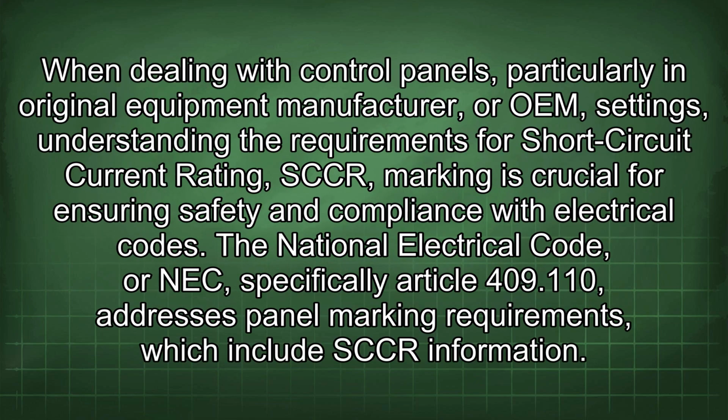When dealing with control panels, particularly in original equipment manufacturer or OEM settings, understanding the requirements for short circuit current rating (SCCR) marking is crucial for ensuring safety and compliance with electrical codes. The National Electrical Code, or NEC, specifically Article 409.110, addresses panel marking requirements, which include SCCR information.